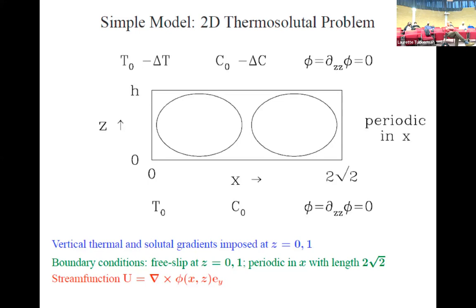And they could drive it in the same direction. You know, hot and cold mix, you do this, whereas cold and hot is stable, or the concentration has the same thing, because we can remember now what convection is. You might think, oh, temperature makes the fluid rise. The hot fluid rises. No, it is density that makes the fluid rise. It is density, and density depends on temperature. But we tend to just shortcut that and say, oh, hot fluid rises. No, light fluid rises. But there's more than one way to make a fluid light. You can make it warm, yes, but you can also use concentration. If your water and alcohol have different concentrations, you will have different density. Okay, so in both cases, it's rho that is driving it.